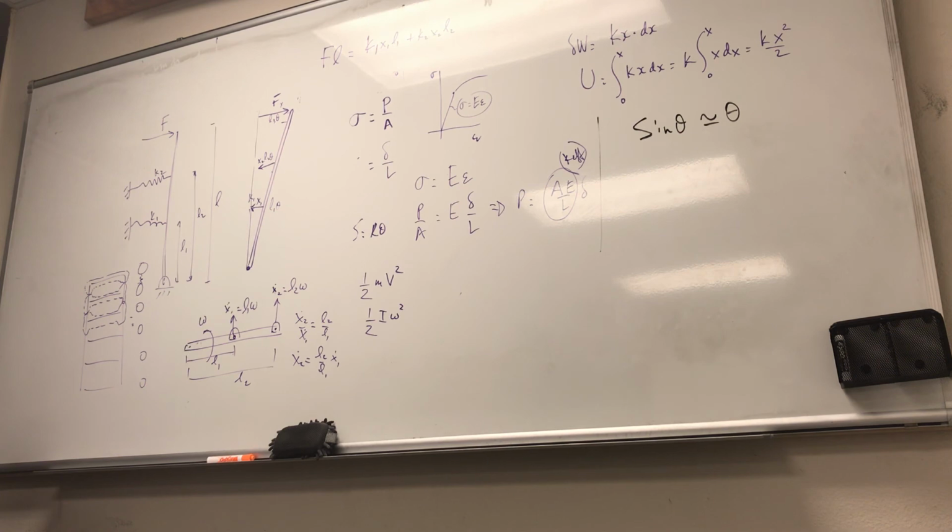The damping force, and this is the key: for a spring, the force is proportional to the deflection of the spring. For a damper, the force that gets developed in the damper is proportional to velocity, the velocity of the 2 ends of the damper. So if the 2 ends of the damper are moved, if there is no velocity within the damper, there's not going to be any damping, right? So a damper is assumed to have neither mass nor elasticity, and the damping force exists only if there is a relative velocity between the 2 ends of the damper.